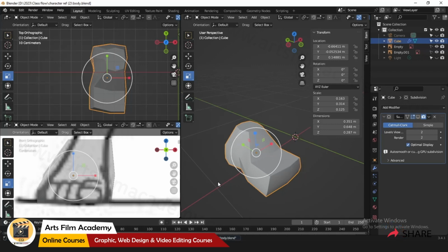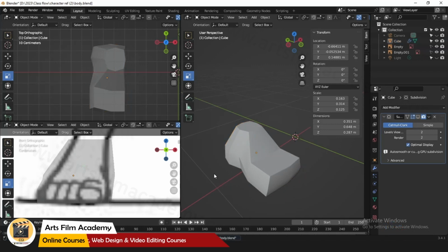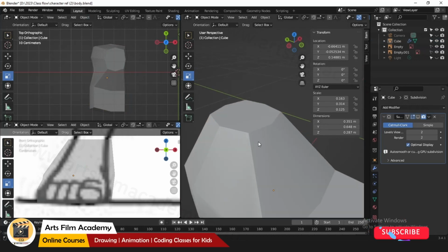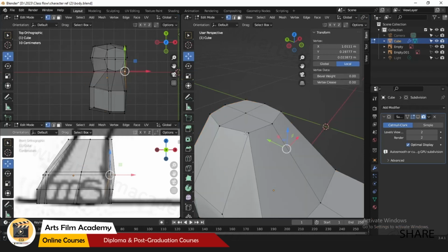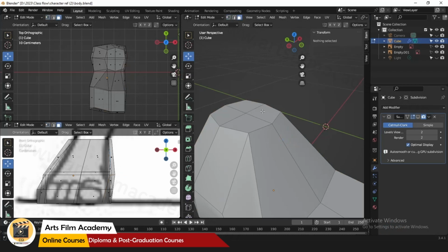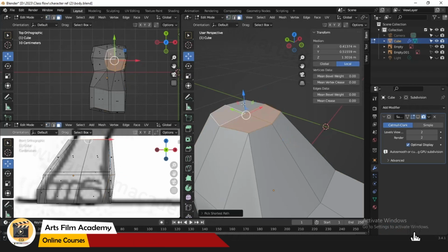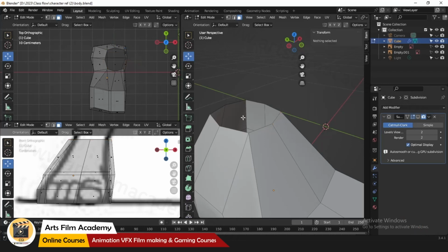So save the file, save as with the file. Always keep 2 copies whenever you complete every stage. Okay, so let's go and extrude the next part. So I'll go for tab. So this is my practice, like I always delete this and later on I will fill. Okay, you even can use this technique or directly extrude from the face itself.